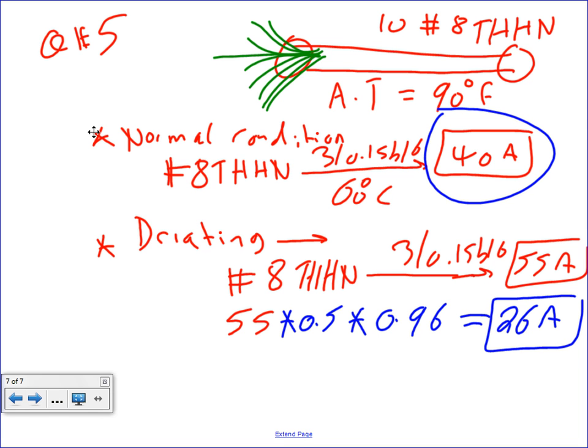0.5 for 10 carrying conductors from table 310.15(B)(3)(a). You see it? 50%. 0.5 is 50%. And then, Chad, for 55 amps, what did we multiply? We multiply it by 310.15(B). No, I mean from 40 amps, which we looked up in the table. One second. 310.15(B)(3)(a). This is coming from that, and this one coming from